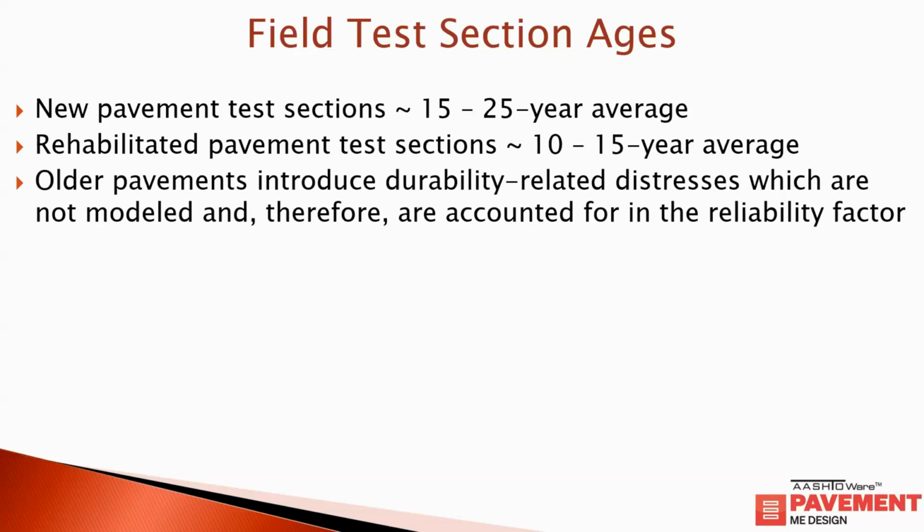So you're going to have normal fatigue-related distress, but then you'll have some contribution from these other factors that you're not directly modeling. But by incorporating that in there, you're basically baking that into the new calibration of the models.